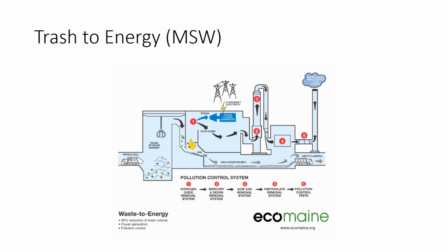Anyway, I digress as per usual, but right, it gets chopped up into tiny little pieces. We burn that trash, which heats the water, generates steam, turns the turbine, and gives us electricity. But of course, you have those emissions that need to be treated, because there are things that get burned that have pretty noxious fumes, not to mention your sulfur oxides, your carbon oxides, your nitrogen oxides. All of those need to either get treated or just emitted, whatever the regulations may be. And then there's the ash that's left over, and that ash could also contain heavy metals and stuff like that.